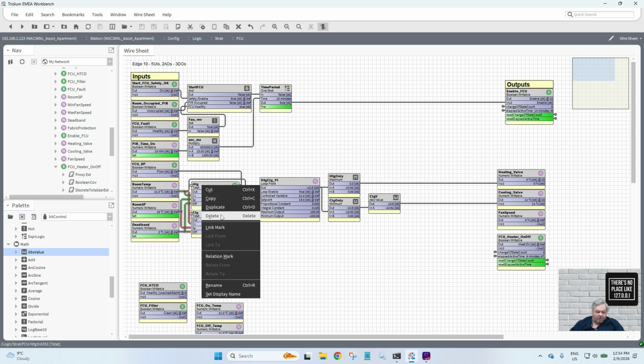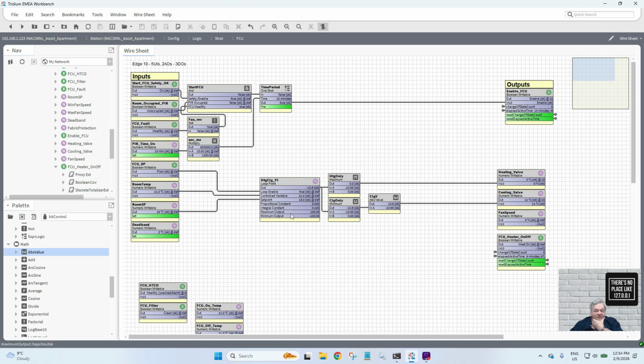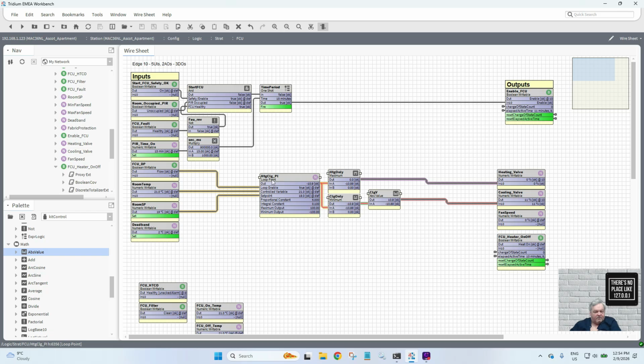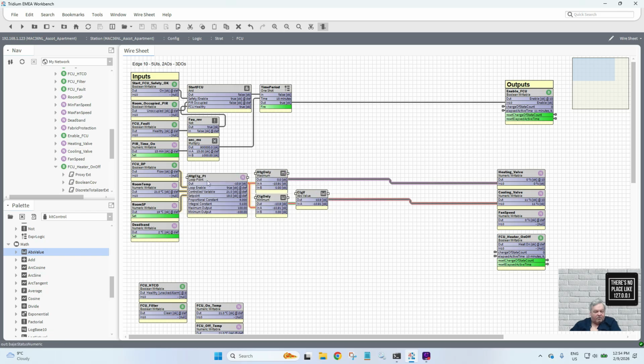Now we might want to quicken up the PI, and do we give the user the option to quicken up the PI, or do we actually have it set and we just change it ourselves? I don't think it'd be wise to give the user that option. But now I'm thinking the dead bands, because what's going to happen there is we're reaching room temperature 21, we want 19.